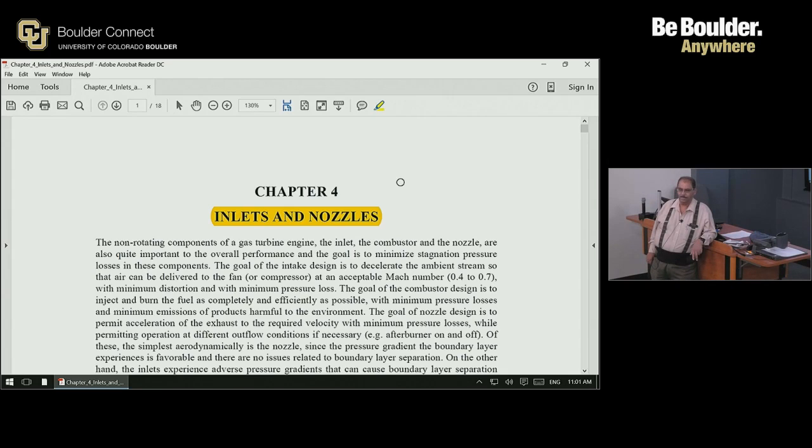One of those is to have hardened blades, and on the casing have soft abradable material, so that the blades abrade it, and therefore the clearance can be very small. The whole point is, if the blade touches the casing and gets stuck, of course it can have an engine failure. So you cannot permit that. But at the same time, you can't have too much clearance. That causes tip leakage and therefore inefficiencies in the performance of the compressor and the turbines.